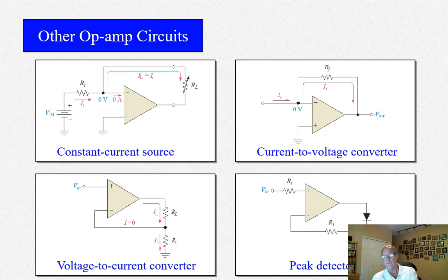Now, if the voltage gets to a certain voltage, let's say 5 volts, and then Vn starts dropping below 5 volts, what happens? Well, this output is below 5 volts. This is 5 volts here at the capacitor, but the output drops. So the diode is back biased, so there's no current flow. Therefore the capacitor holds that peak of 5 volts.